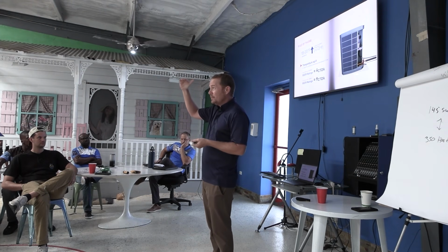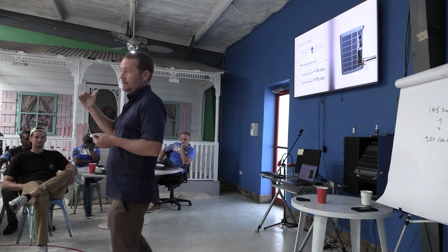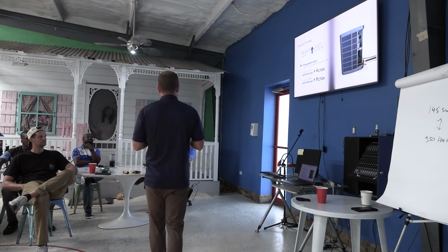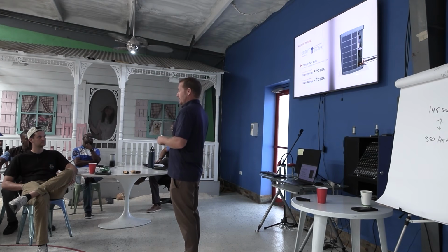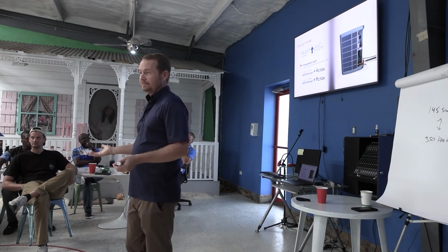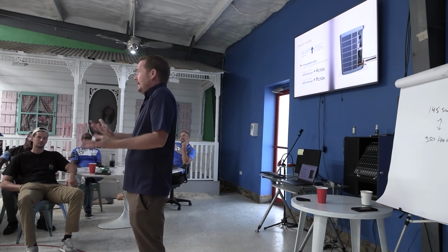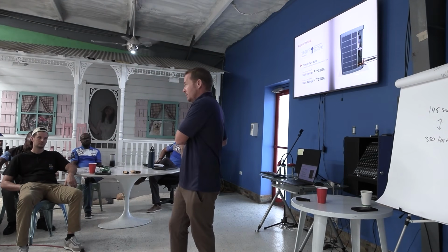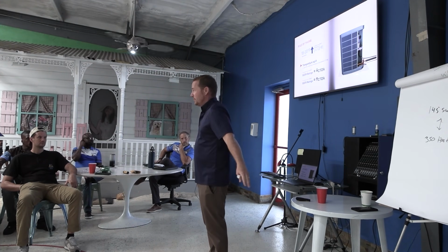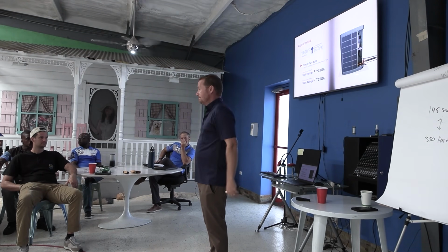But holding the head pressure down is a good thing, no matter what, right? We do not want elevated head pressure for no reason. So let's do something specific to your market. When a condenser coil is in the salt air and all the fins fall off and there's just tubes left, what happens to your head pressure? It goes up really high, right? Because you're not able to get the heat out of that condenser. The condenser is the heat rejector. We want to get heat out of it. If the heat stays in it, what happens to your head pressure? It stays up, right? Hotter condenser equals higher head pressure, and we don't want that.